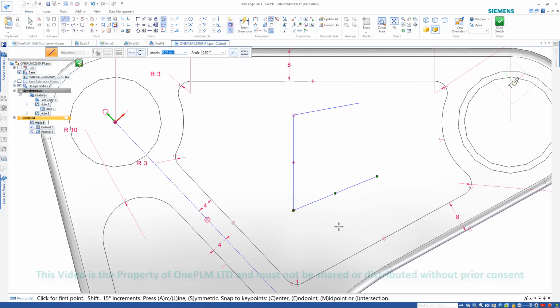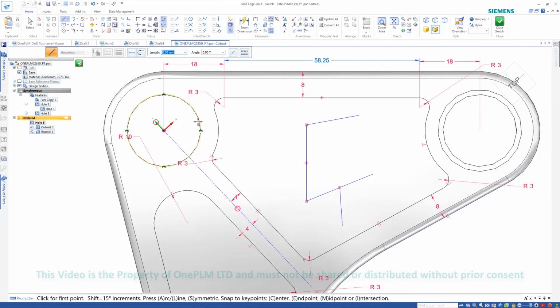So we've got M, where it'll go and snap to the mid position. So I'll click on that one, and so I'm not doing anything with the mouse, I'm just moving the mouse, hover over the line so it goes orange, click M, that is then going to go and snap that to that position on there. If I want to go and snap to a center position as well, hover over, don't actually go over the center, hover over the line itself and press C, that will then go and take it to there.